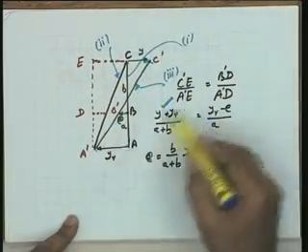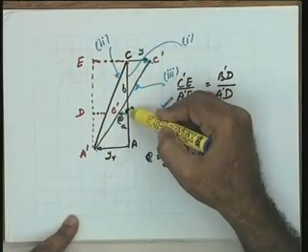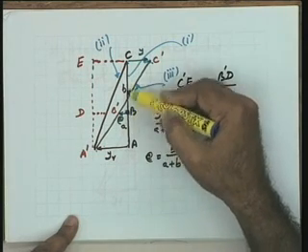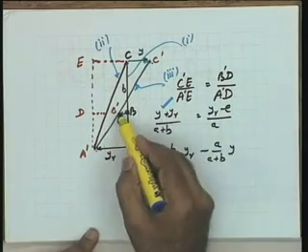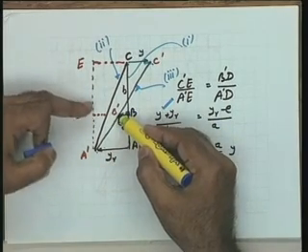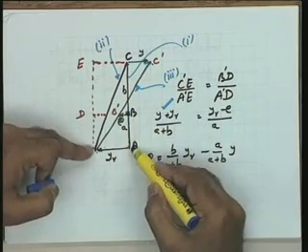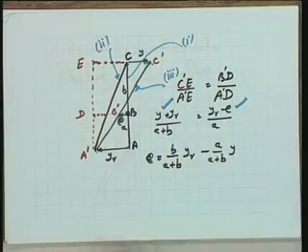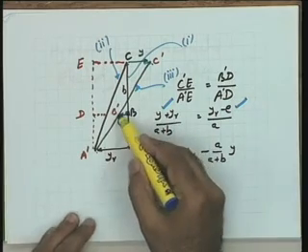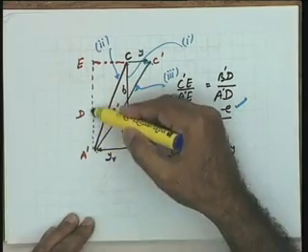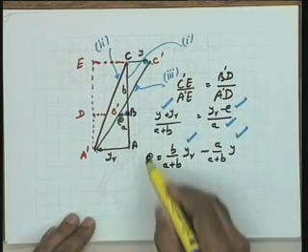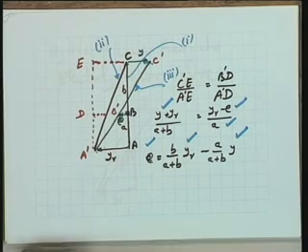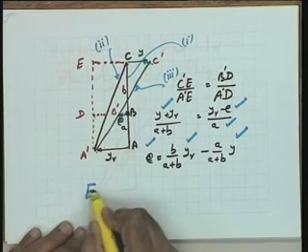And how about A dash E? It is A plus B, where A and B are the two dimensions of the lever with respect to the spool position. So, look at this quantity, B dash D is equal to yr minus E, which should be clear from the geometry. Yr minus E is equal to B dash D, and this distance is equal to A, and therefore E in terms of yr and y is given by this expression.